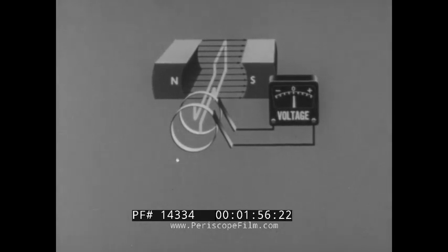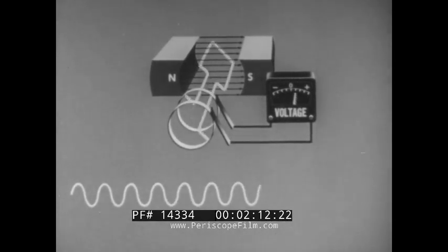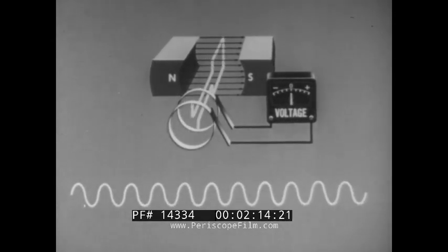One complete revolution of the armature will produce one cycle of alternating voltage. If the armature rotates once each second, the frequency of the alternating electromotive force or voltage is 1 cycle per second. 10 mechanical revolutions of the armature per second produce a frequency of 10 cycles per second. Frequency, or the number of cycles per period of time, is directly related to the rotating speed.